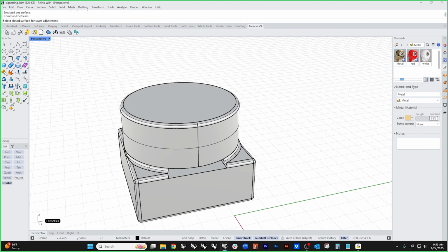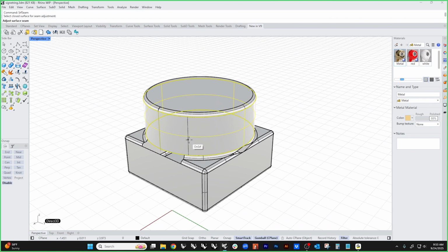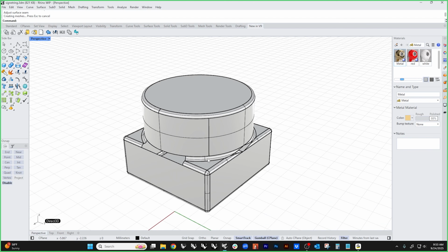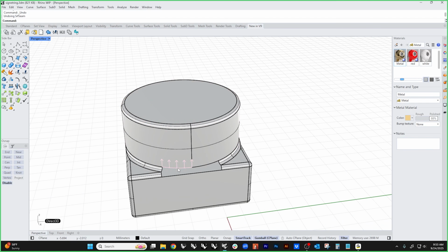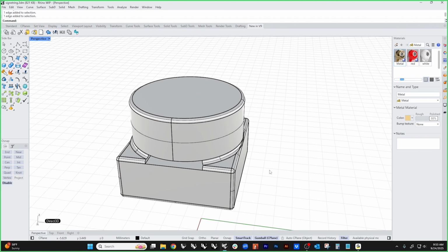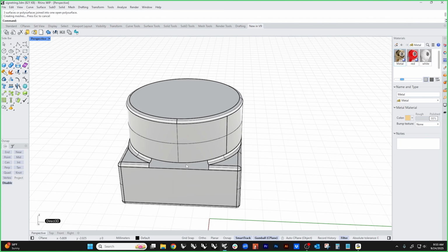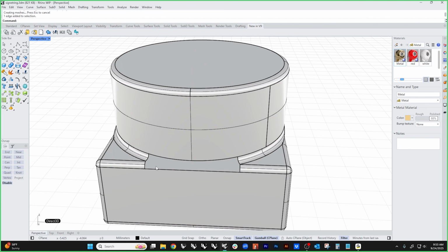There's a command in Rhino called surf seam that tons of people don't know about. So if you have the seam, right? Because the seam, what was happening is this is two edges. I don't want two edges. I want the seam to not be there. So I'm going to move it someplace else where it's not in the way. And now I've got one edge.